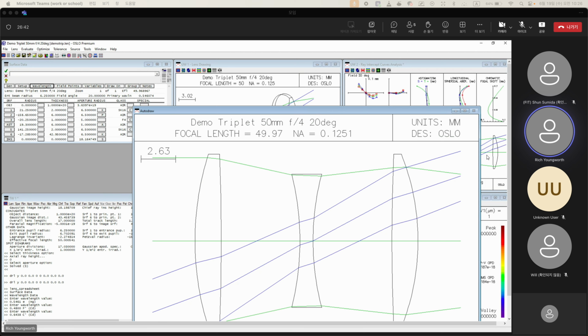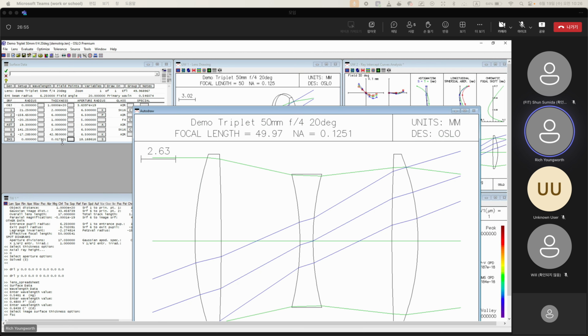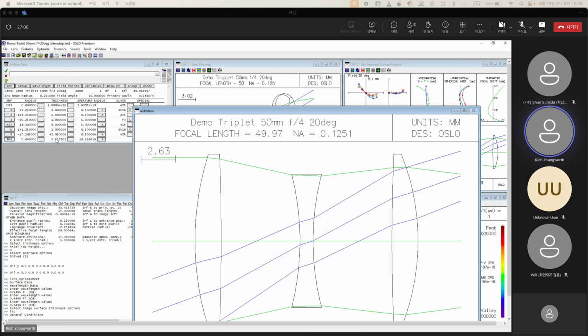When we do this, that's the wavelength order. Now it says performed a spot size autofocus. So that's where we come down to here. And this is another type of solve. Spot size, field average, polychromatic is what we'll do. And so it wants to shift it 17.8 micrometers is how far that wants to shift. Now I know this is in millimeters because my general is in millimeters. So you get pretty used to just multiplying by 1,000 and calling that microns when numbers are small like this.